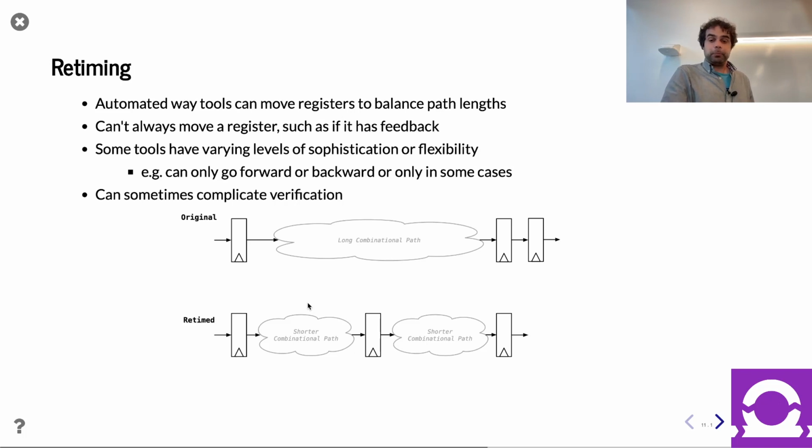One of the other challenges of retiming is that now you change the semantics of the internal registers. Even if your design has the correct result, it may complicate your verification team's efforts, because if they now want to verify your design or do logical equivalence checks, it's a little bit complicated. Once again, the expensive, pricey commercial tools have solutions for this. But for those of us living in the open source world, we can only dream about that right now. Cool. Other questions? Yes.